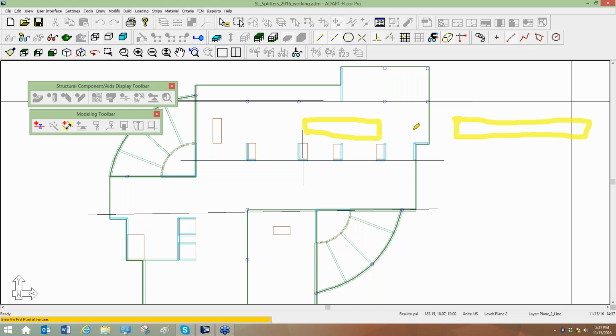There's a big opening there, and then it does this. So there's clearly a discontinuity in the design, the physical section cut, but the program actually translates this into a cut that is combined. So it's taking the integrated action over the shells represented by this area on one side, and it's taking the integrated actions by the shells on this side, and it's basically mashing them together into one cut.